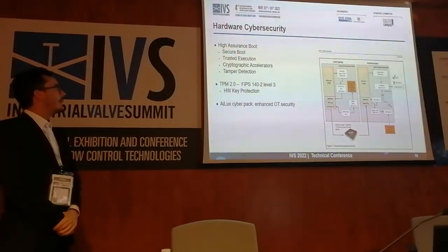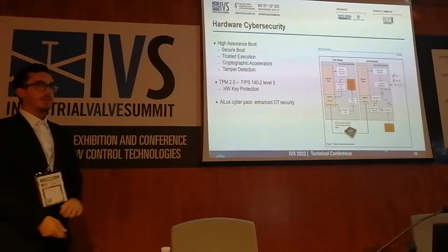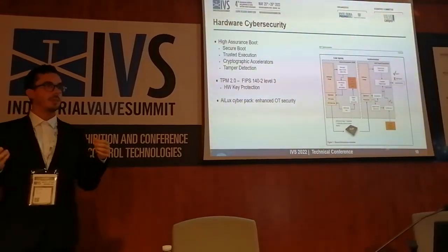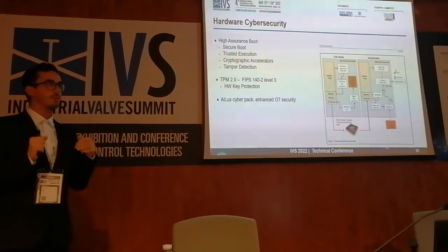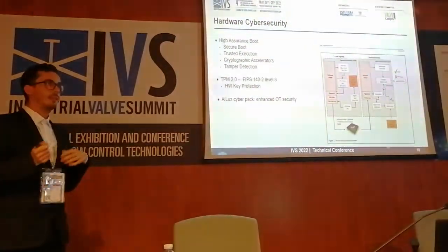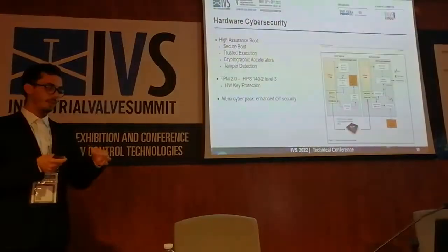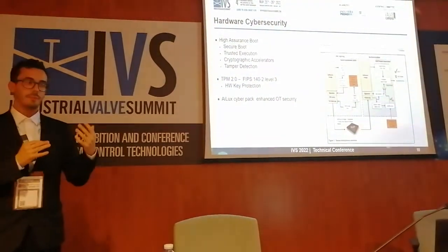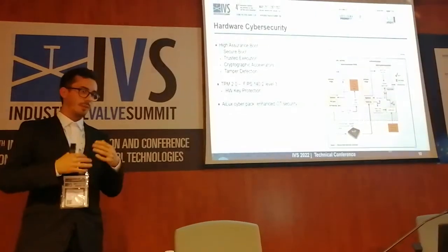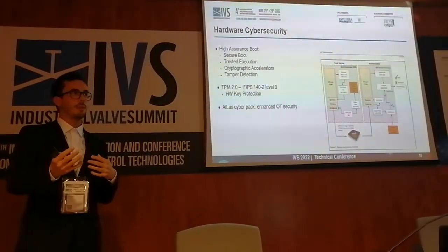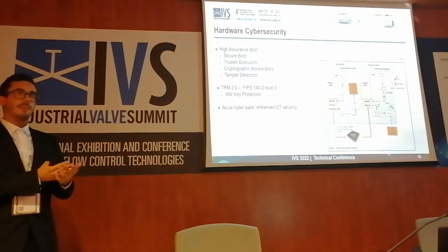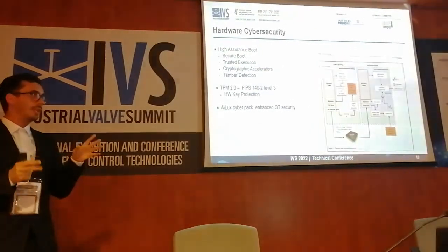And there is also the tamper detection. Tamper detection means that if something happens, for example, somebody tries to open a device when it's not supposed to be opened, or somebody takes off the temporary battery, there is the first level that is a warning. But if you want to go further, you can provide also a hardware way to delete and to erase everything that is concerned in cybersecurity.